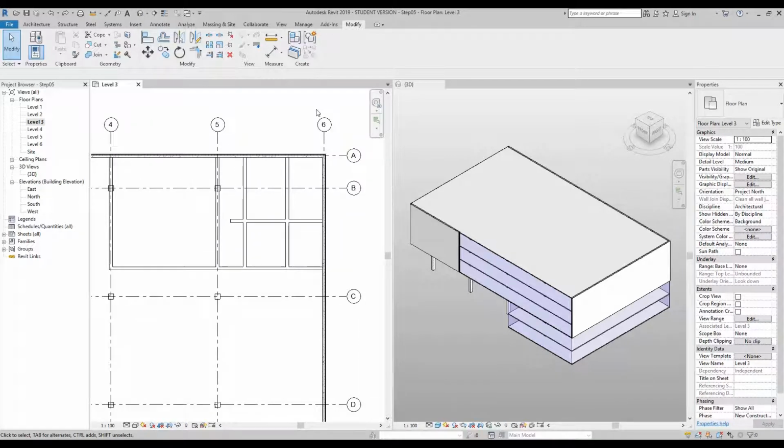The next trim and extend tool I'm going to show you is between the 2 previous ones, which is trim, extend, single element. Press this button. I want you to hover over the horizontal wall that is currently between grid lines B and C, this one here. I want you to highlight by hovering over the south side of this wall so it's blue. Click once, and then the wall directly above it, click once more, and you will notice we've closed off this